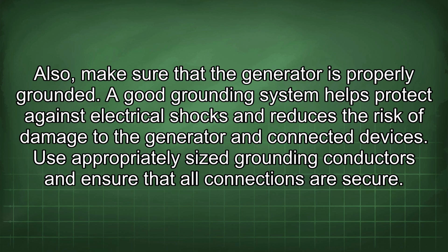Also, make sure that the generator is properly grounded. A good grounding system helps protect against electrical shocks and reduces the risk of damage to the generator and connected devices. Use appropriately sized grounding conductors and ensure that all connections are secure.